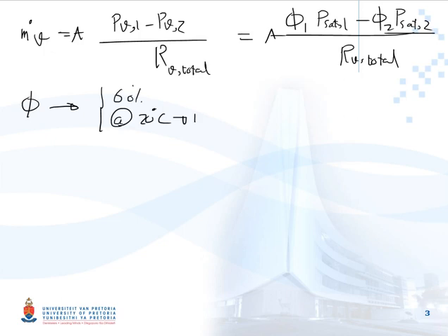What table was that? 14.6, am I right? Please go and check it. I think it was 14.9 if I'm not mistaken. Go to table 14.9 and we read it, and the saturation pressure at 20 degrees will be equal to 2339 Pascal.